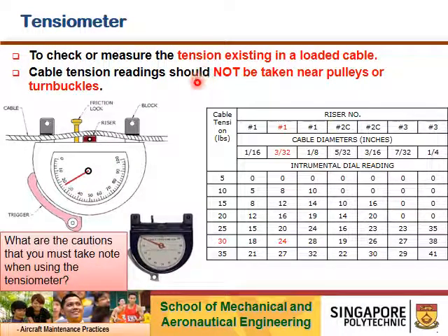Do take note that we do not use the tensionometer near the pulleys or turnbuckles. You engage the tensionometer far away from the pulleys or turnbuckles to give you a more accurate reading. For that, you need to know there is a riser to choose. This chart will be given by the tensionometer manufacturer.